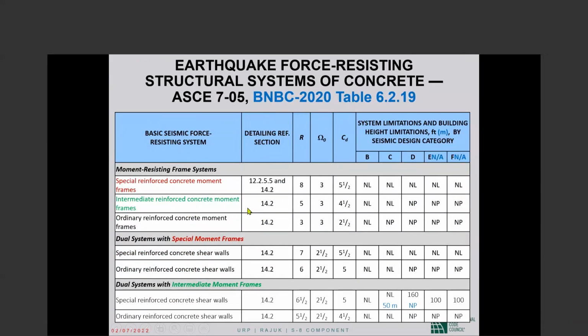Almost for all concrete systems, the reference is 14.2. Section 14.2 of ASCE 7 simply references ACI 318. So the detailing rules are to be found in ACI 318, and those rules I will discuss with you starting tomorrow, actually.